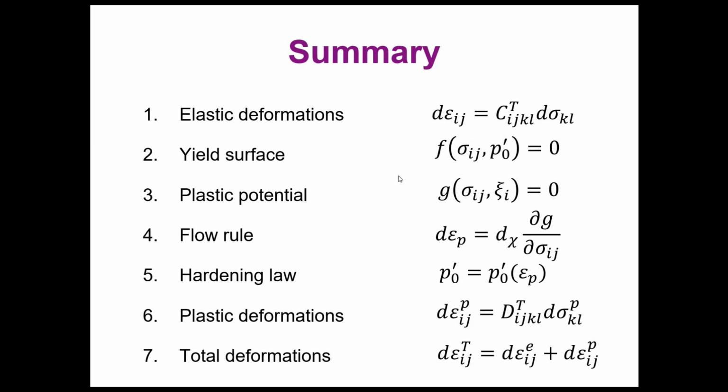of your plastic deformation. And you need a flow rule to establish the value of this plastic deformation that will allow you to calculate the total plastic deformation that will have components, of course, but they are dependent on each other. You need a hardening law to establish in which way the plastic yield strength grows, or any other set of parameters your plastic theory needs in order to have control in this increment or decrement, if you have softening.